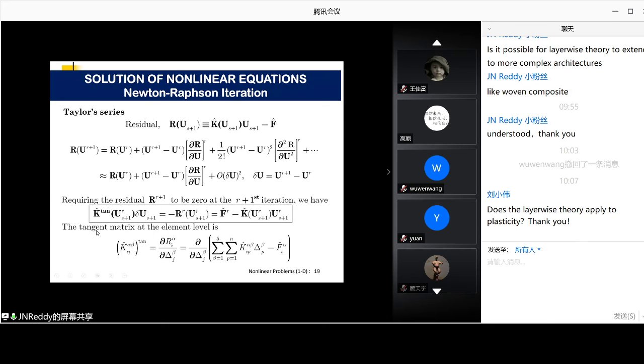Okay. So remember, if you don't update K, you must still update the residual, that you cannot stop doing. Then you won't get any new solution. So you must update the residual, but you may not update the tangent matrix. Okay. But you still have to update it after a few iterations. If you never update it, you get a wrong solution, or it never will converge.